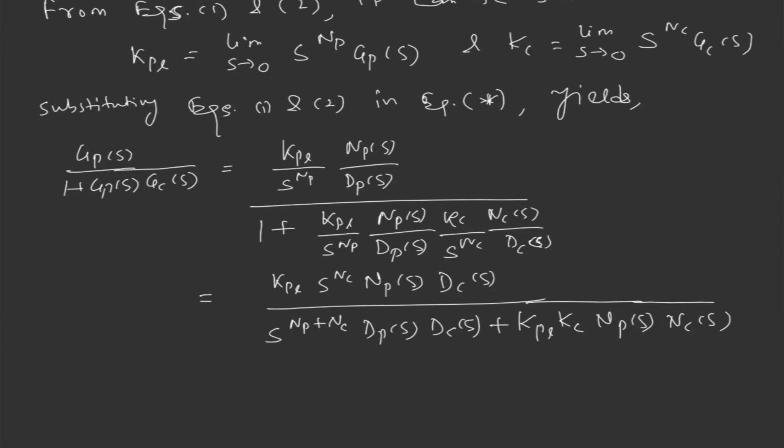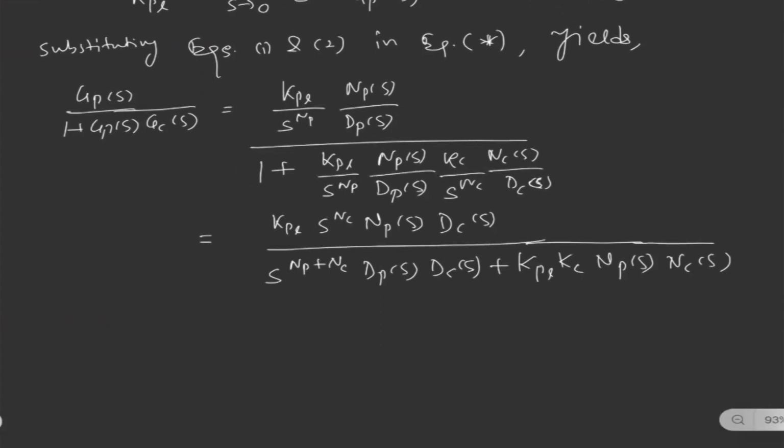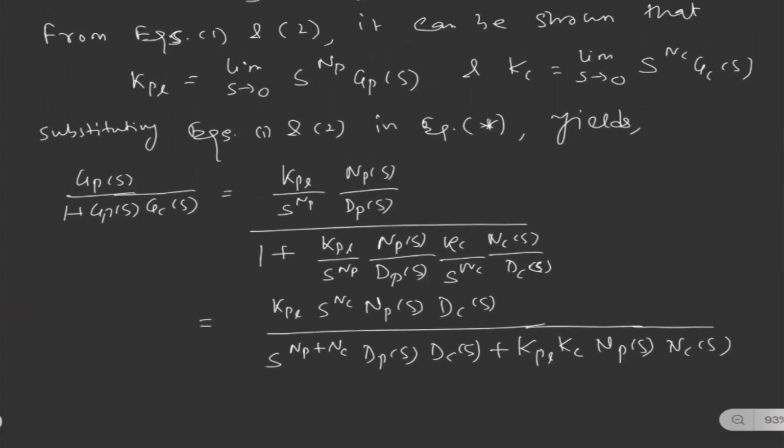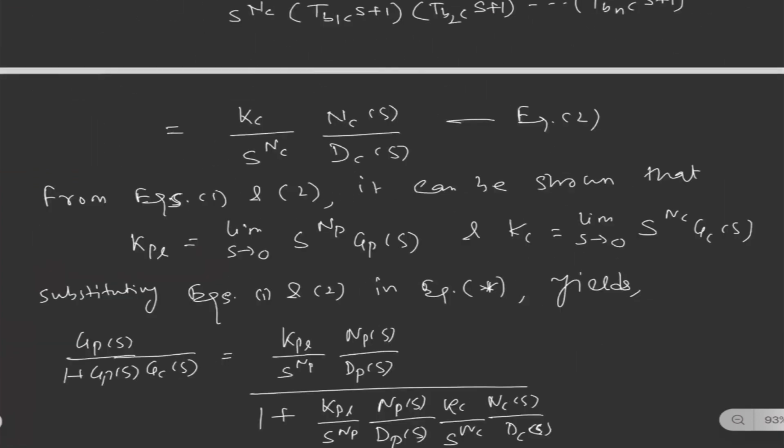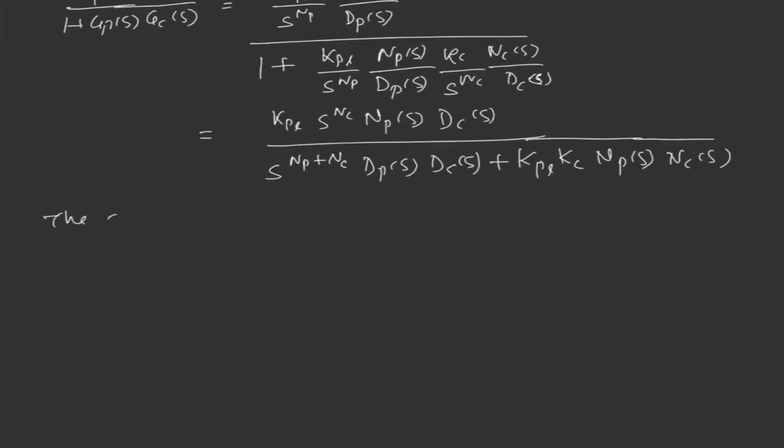Because if you remember in our earlier lecture we have discussed, due to the presence of the integral term in the PID controller, we can ignore the disturbance effect in the system. This is the direction we are moving here. How we can come up with the integral term in the system and how it is going to affect our steady state error due to the disturbance.